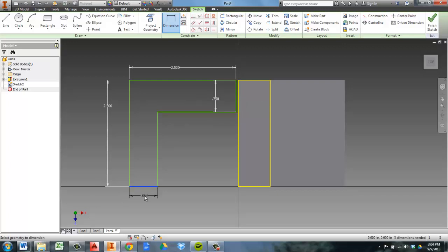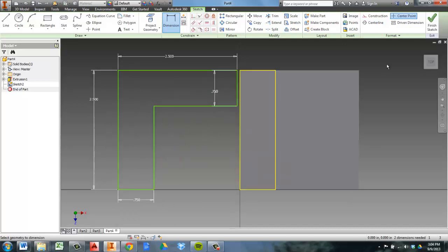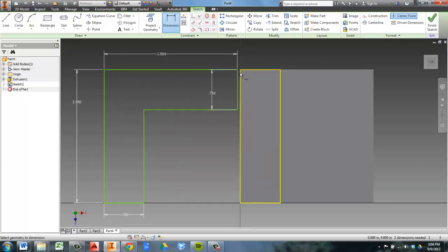Once I've done that, actually reconstrain. Okay. So we've got these dimensions here. I also want to place this. All right. I also want to give this a particular location within space. Notice there's a gap between these two parts. I want those to actually be connected. I want this to have zero distance between this line and the back side of this.